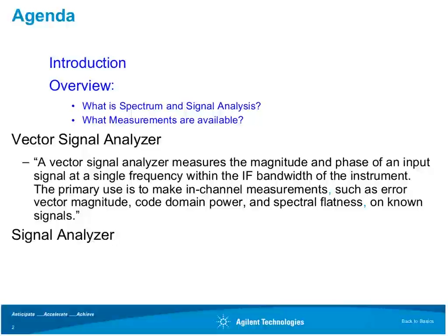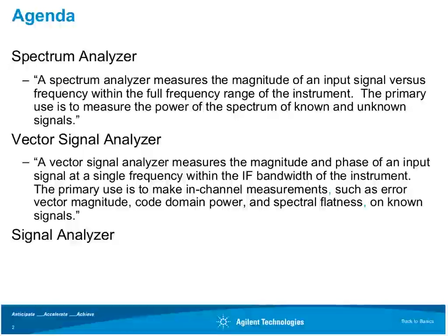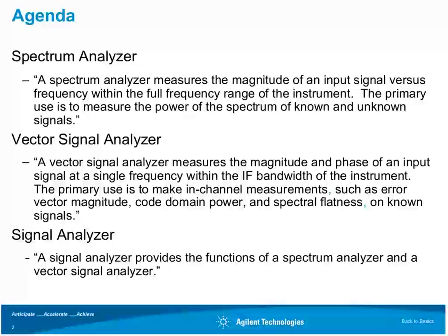So a good place to start out is to talk about a few definitions. Now, a spectrum analyzer, classically, is an instrument that gives you an indication or a measure of the amplitude of a signal versus frequency. That's really a scalar type measurement, scalar information, and that's how spectrum analyzers first began some 50 years ago with this kind of capability.